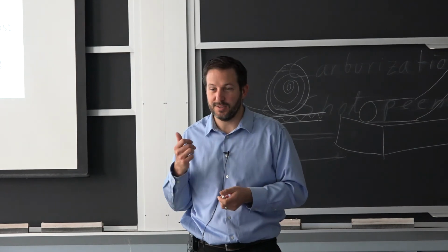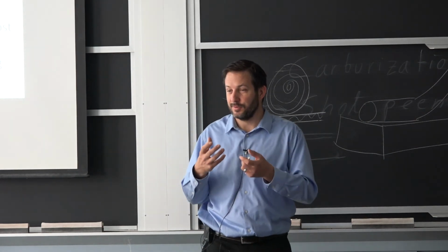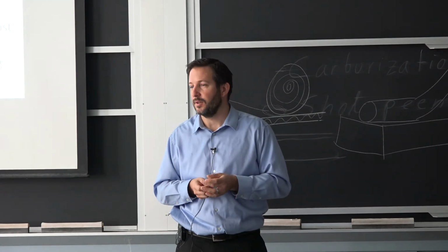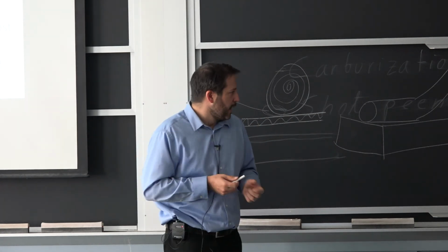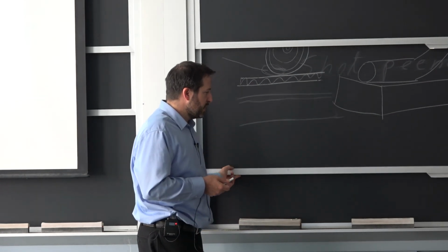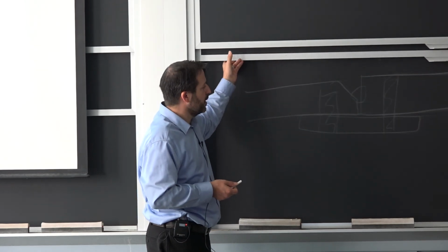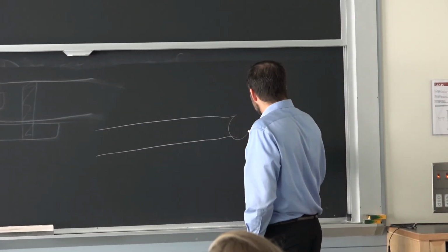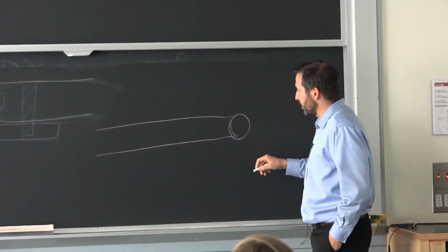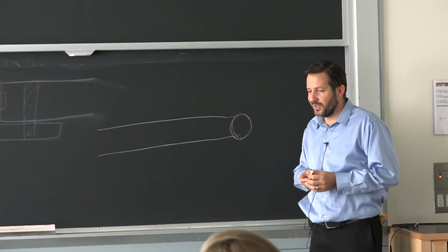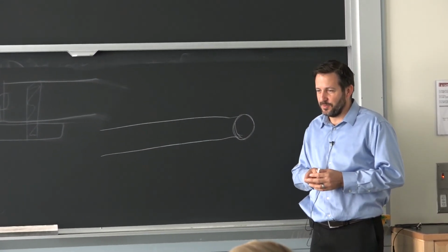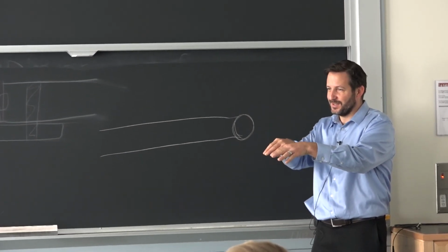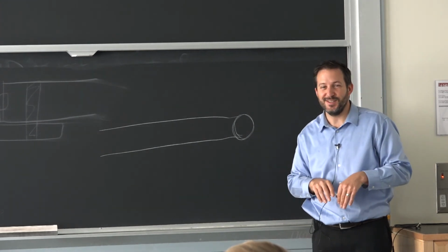You cast, in this case, you don't deform it. So this structure in the center, you can do a heat treatment, but you can't really deform it. Although, I know that sometimes these days when they talk about seamless pipe, and that probably is the best way to go now for a discussion, there's a specification for seamless pipe that is very clear that it doesn't mean that you didn't start from a plate and make it into a shape. All it says very clearly is you can't see the welded seam.